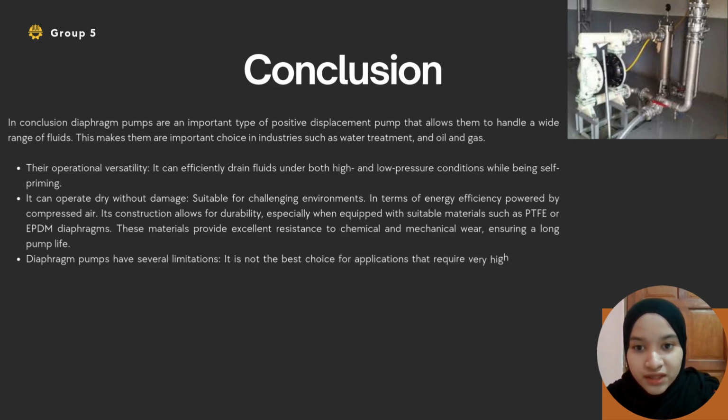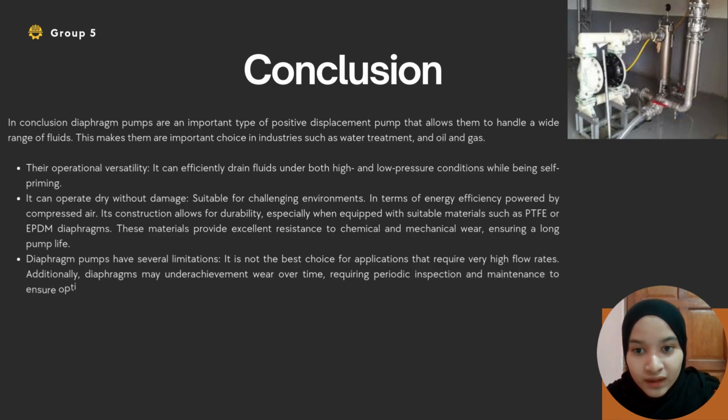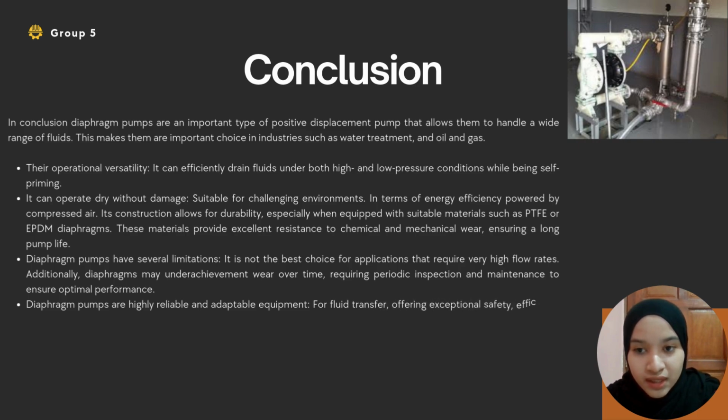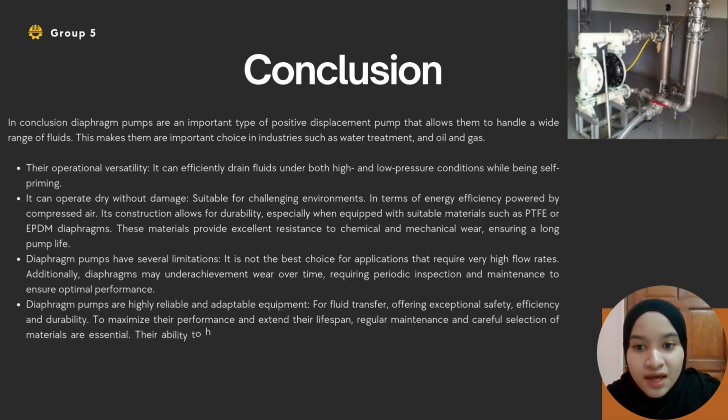In terms of energy efficiency, the diaphragm pumps are designed to operate effectively when powered by compressed air. Its construction allows for durability, especially when equipped with suitable materials such as PTFE or EPDM diaphragm. This material provides excellent resistance to chemical and mechanical wear, ensuring a long pump life.